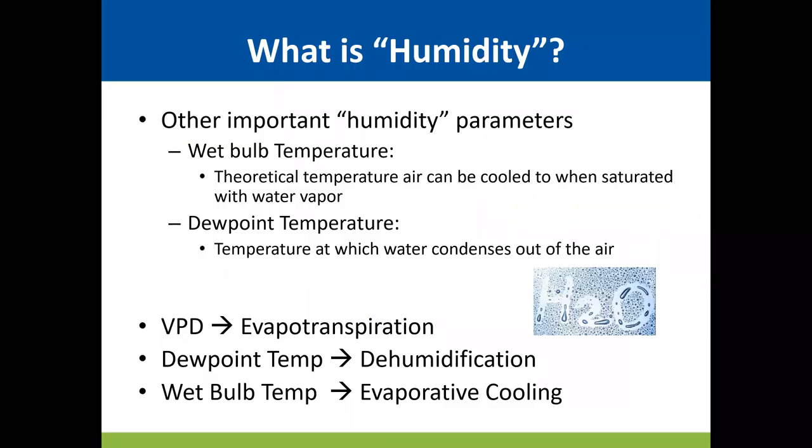Now, I'm going to come back to that in a second. Other important humidity parameters that all of us should be aware of are, one, wet bulb temperature. This is the theoretical temperature at which air can be cooled to saturation when we add water vapor to it, okay? This is the process of evaporative cooling. The dew point temperature is the temperature at which water condenses out of the air.